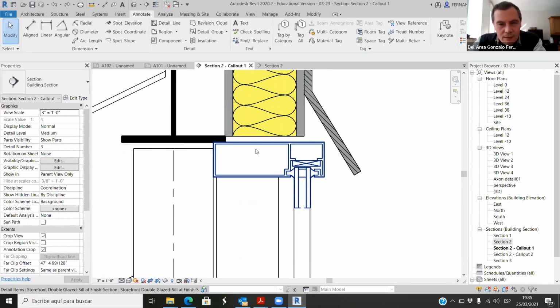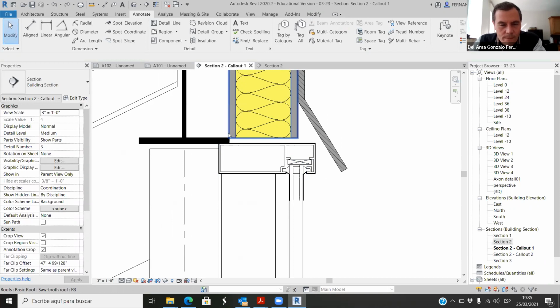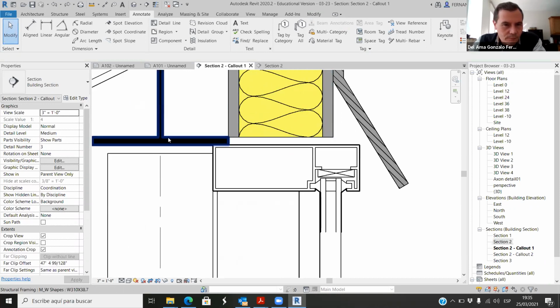When we have this, we have to seal, because this is the roof panel. Here we have this, and this always happens when I was talking in 360 in solar design or building science too about air leakage. Okay, this is an air leakage, or this has an air leakage potential, because the air can go through this crack. This is very small. It's a quarter of an inch or even less, so it's almost nothing. But if the wind blows, it will end up entering through this element here.